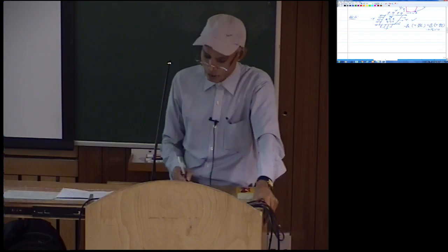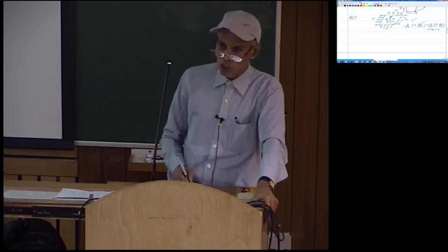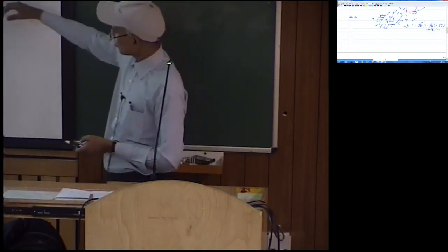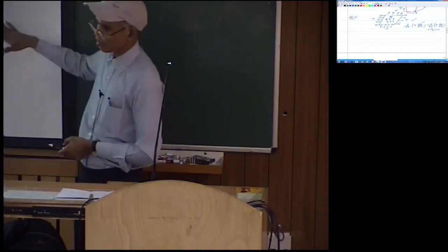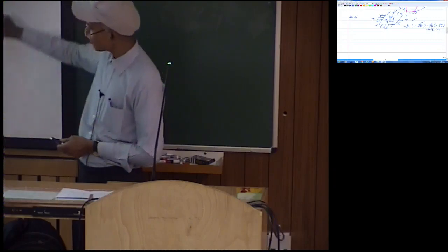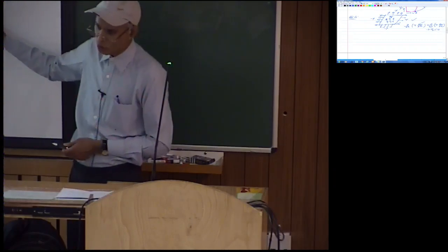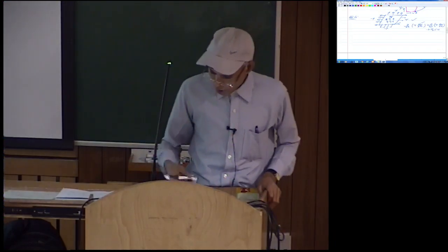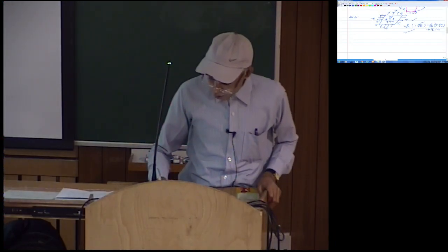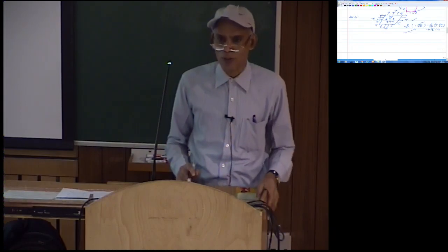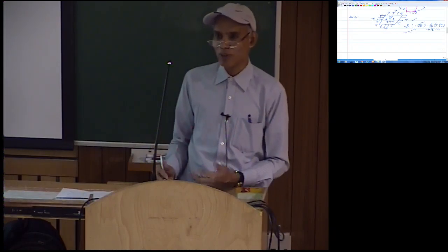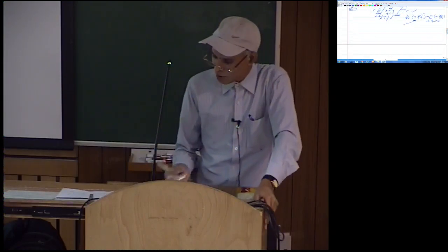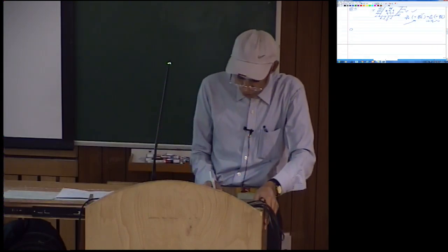So this was the differential equation where w is the transverse displacement, that is, displacement transverse to this, like in this case w is the displacement in this direction, t is the in-plane tension, and the load q is in the transverse direction. So this was anyway, if you look at it, exactly what we had discussed as heat transfer problems, only thing is physically the problem is different, otherwise the differential equation is of the same format. We had discussed this, so I expected you all to actually do this.